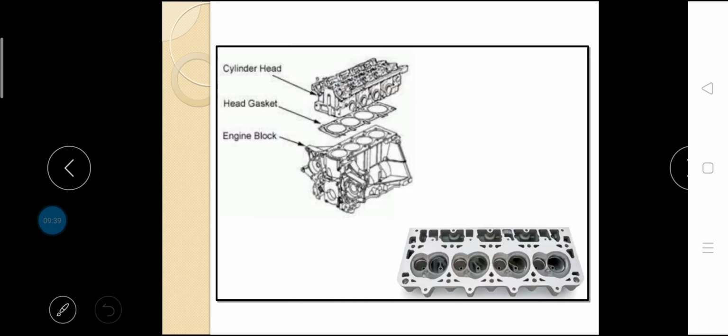Further, the detachable head types have many other advantages over the integral construction. From production point of view, the cylinder block casting with open bore for the detachable type head is much more simplified. Operations like decarburizing and valve grinding are simplified. The compression ratio can be changed slightly by changing the thickness of the gasket used between the block and the head. The materials that are generally used for cylinder heads are cast iron and aluminum alloy.